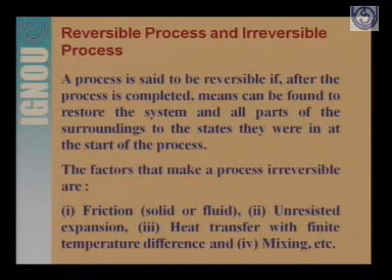A process is said to be reversible if, after the process is complete, means can be found to restore the system and all parts of the surroundings to the states they were in at the start of the process. But in reality, most processes are irreversible, and only for a mathematical model can we think of a reversible process. In practice, whatever process we can think of, like heat transfer between two definite temperatures, cooling of hot milk in an environment, or burning of coal, these are all irreversible processes.